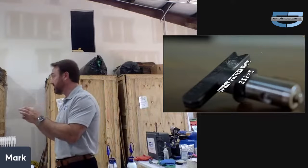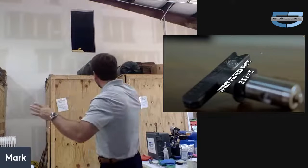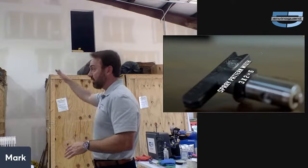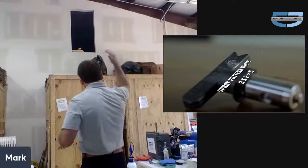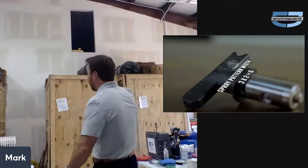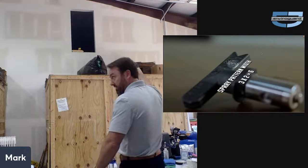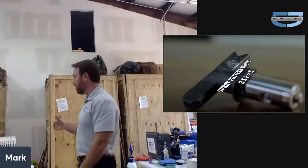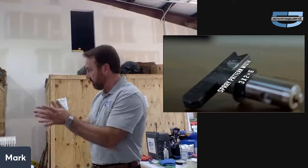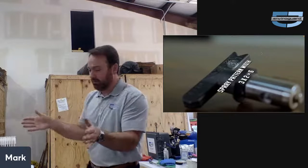Don't think that you're stuck with an out-of-the-box tip. If you've got a broad wall, if we were doing these walls right here, I would have a 12, 19 or something like that all day long, and we would have, of course, everything in place so we could do it, but we would just work our way across that, and in a matter of minutes, we would have this thing sprayed out, as compared to the many, many minutes that it would take if we were just working with something with a much narrower fan pattern.